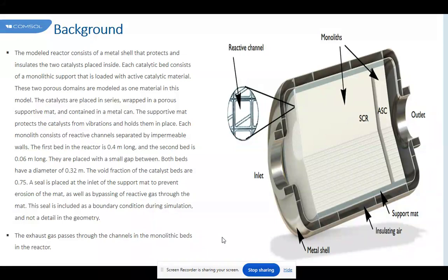Although this change is small, together with the inlet velocity, it led to a channel apparent velocity in the 400 per 6.5 monolith almost twice higher than that in the 900 per 2.5 monolith. Such a combination of factors is quite consistent with the results in the simulation, and this simulation shows the reaction rate for the four combinations of ring and core monoliths where both had the same volume. The profiles are consistent with the results in the simulation.